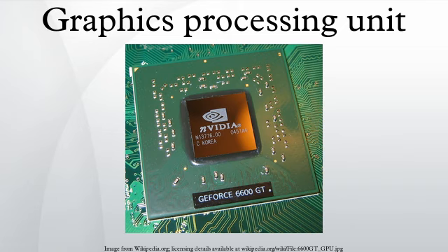Video decoding processes that can be accelerated. The video decoding processes that can be accelerated by today's modern GPU hardware are motion compensation, inverse discrete cosine transform, inverse telecine 3:2 and 2:2 pull-down correction, inverse modified discrete cosine transform, in-loop deblocking filter, intra-frame prediction, inverse quantization, variable-length decoding, more commonly known as slice-level acceleration, spatial-temporal deinterlacing and automatic interlace/progressive source detection, bitstream processing and perfect pixel positioning.